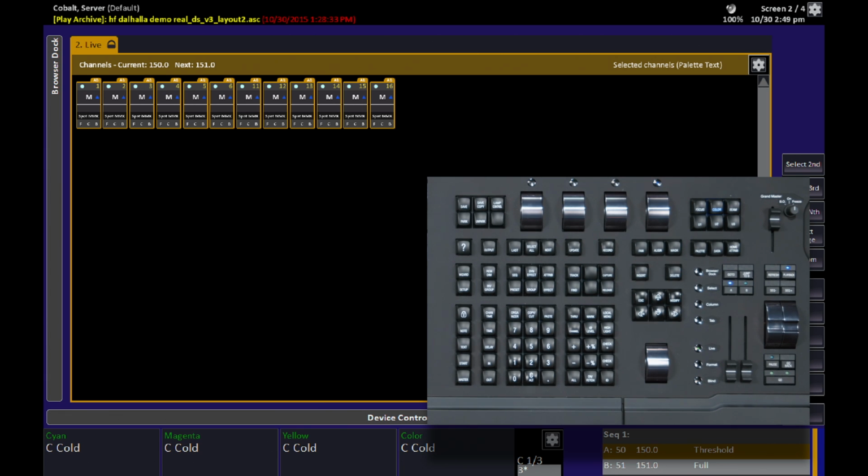If I want to remove a group from a selection, the command is group and minus. So I can deselect group 2 from the selection, 2, group and minus, or use the at mode command, which would simply be -2. Depending on your selection order, if you selected groups and then channels and then groups again, the at mode method might be -group 2.